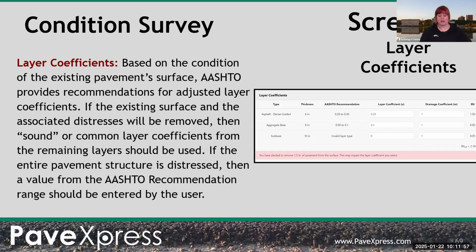And then we got another one. How would somebody determine the percentage to put in for that amount of cracks? That depends on your condition survey. So you've got to go out and look at it. You look at your pavement and its percent of area and things like that. I can show you some of that stuff when we go through there. But basically it's a condition assessment.